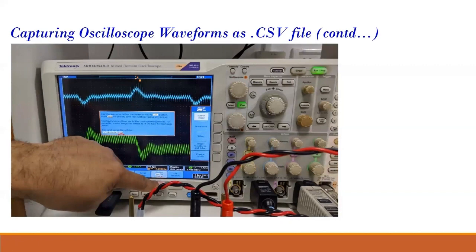Sir, this voltage waveform and this inductor current waveform we are taking from the DSO. Since it is not starting from 0, we are offsetting it and comparing with the MATLAB simulated waveform. Sir, the lowest points of the inductor current at all instances, in our simulation and DSO, are they matching? They are approximately matching, yes.